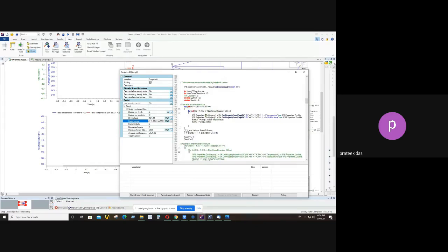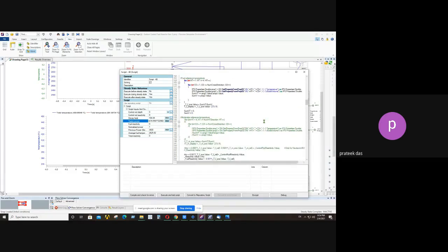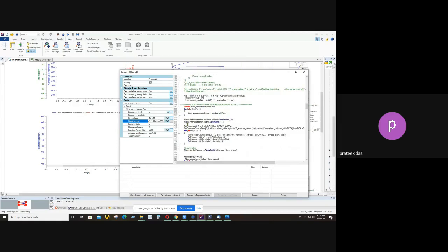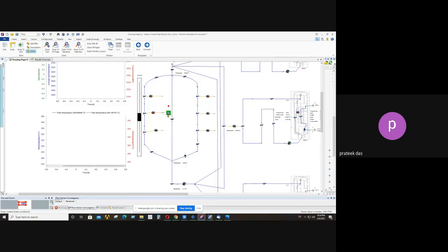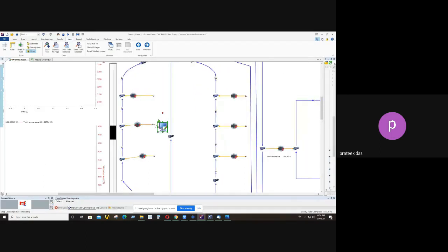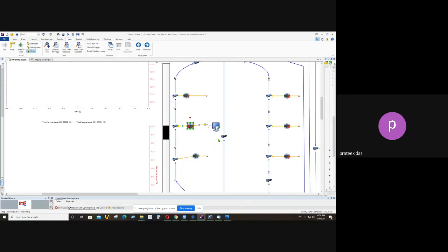You just have to specify your reaction and reaction rate and all the variables which are going to be used to calculate all those reactions. Then you can also integrate the xenon poisoning, or the amount of iodine generation, throughout this cycle. This model has been pre-built as a simple network like the point kinetic neutronics model, and from this it is going to calculate the total amount of heat generation.